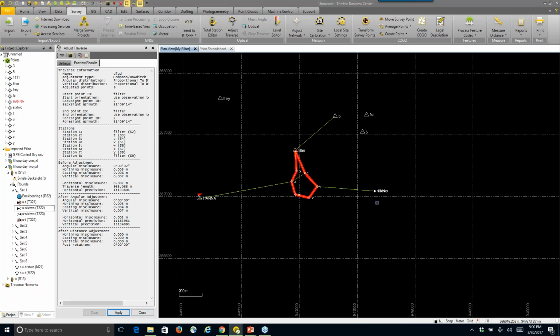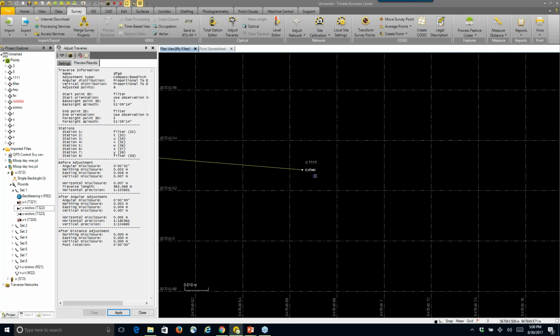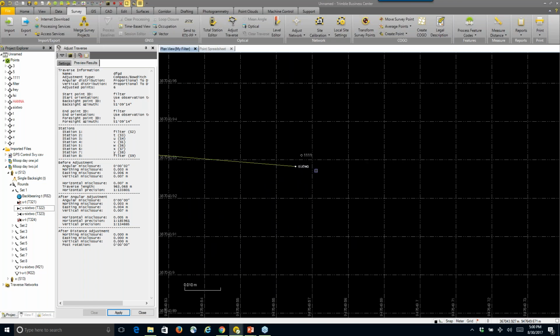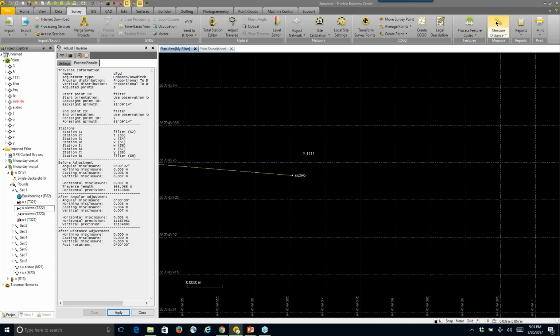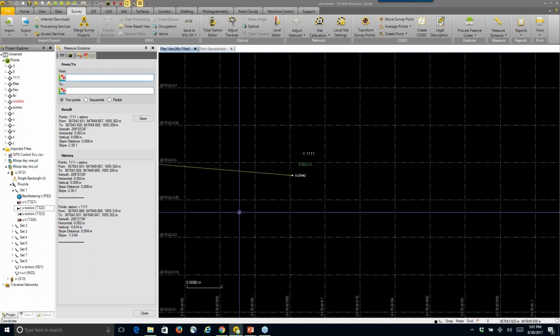Okay. So while you're doing that, Terry, can you have multiple least squares adjustments in the same TBC file? No, you cannot. One adjustment per file. Now you can see in this case the traverse adjustment adjusted the point a little bit differently, and it put it to the south of the initial location of point 62. And how much did it move it? 3 millimeters, while the least squares adjustment adjusted it a lot more.